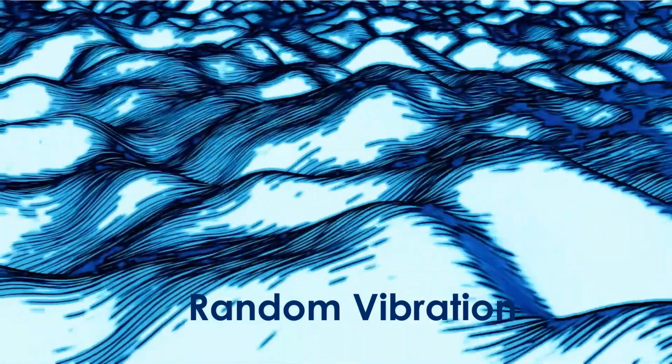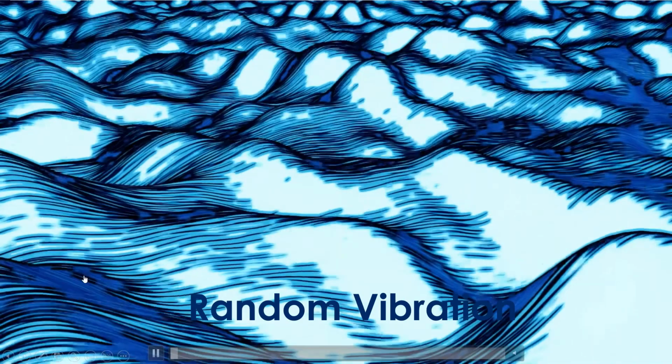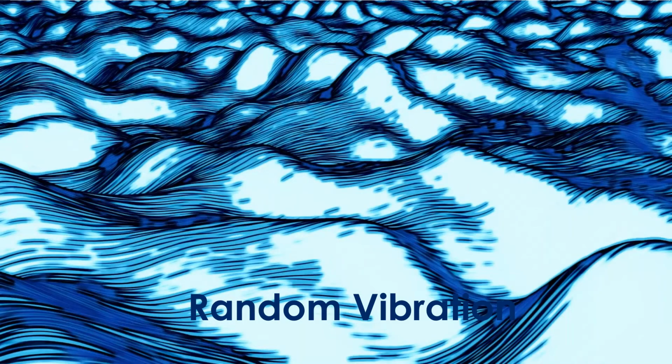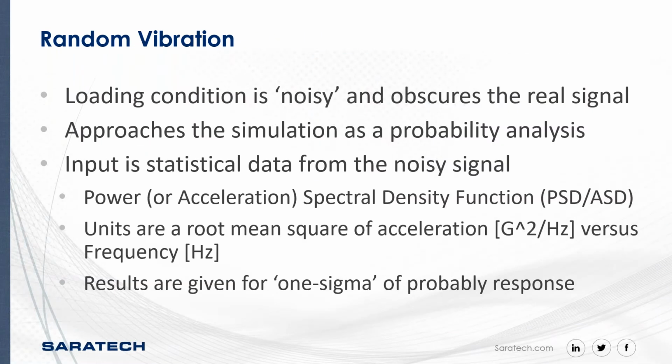Next, we get into random vibration. As you can see here from the input, we've got a lot of overlapping signals with each other, so much so that we can't quite identify the different inputs. And so in this situation, we have a random vibration. Random vibrations are used for when our loading conditions are noisy and obscure the real signal. So instead of a direct approach, we take a probability analysis on this.